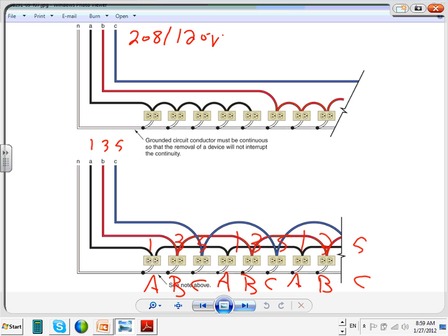So if Nick is plugging into 3 receptacles, these 3 receptacles will be from 3 circuits. So he's not overloading one circuit, since each receptacle is fed from a different circuit. It takes into consideration the diversity of the load, guys. Long story short, if you do it this way, it would not overload your 20 amp circuits. The best way to do it is this way.